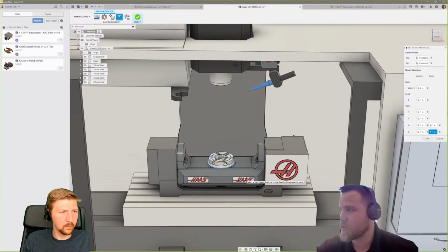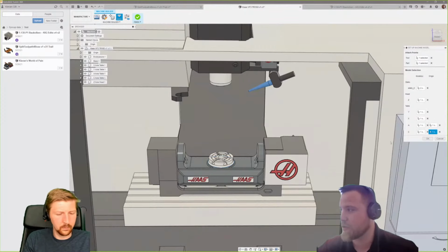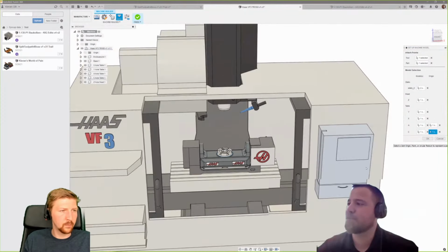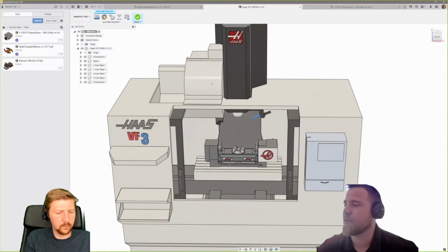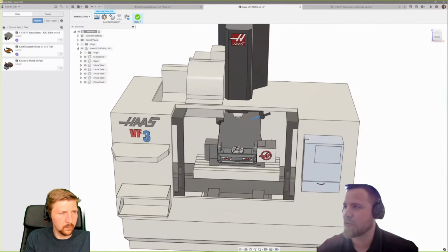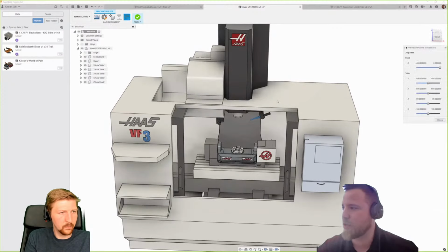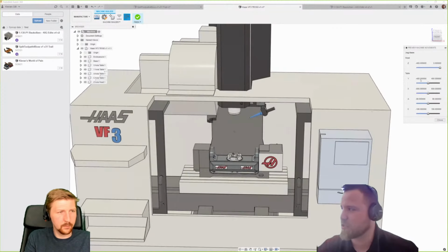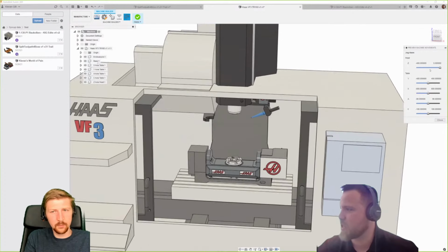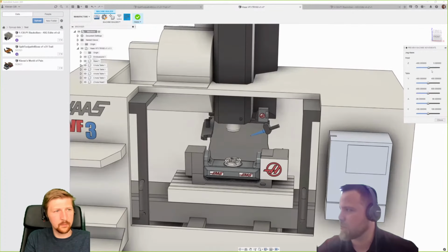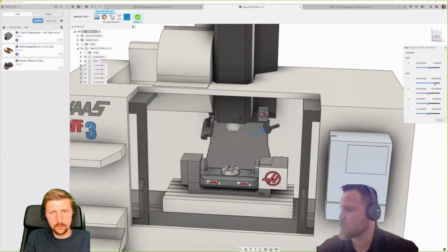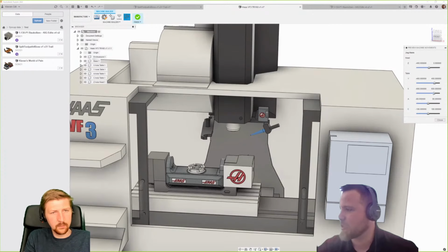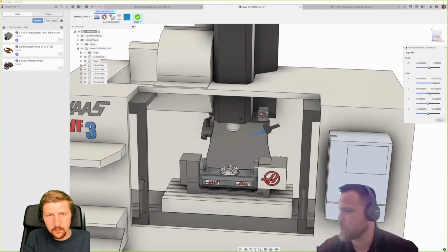Okay. So we've defined everything. Let's click on OK. But do we know if we've done it correctly? Fortunately, there is a little jogging button on top here, which allows us to simulate jogging some of these axes to see what's going on. So let's drop the z-axis down a bit. We can see that moves okay. Let's start jogging the y-axis back and forth, and that moves okay. Let's jog that forward and then start moving the x-axis along as well, and that moves okay.